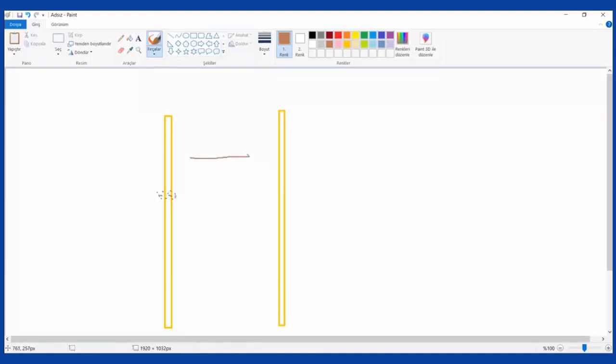So if we have a really big distance between boreholes, let's say 200 meter, then if we don't use uncertainty level or the beta value to adjust our implicit modeling entries to our project, it's going to produce some points, but it will consider them as separate points.